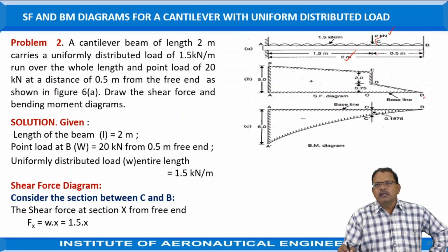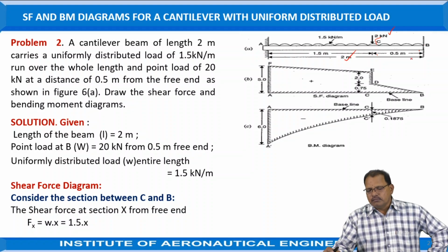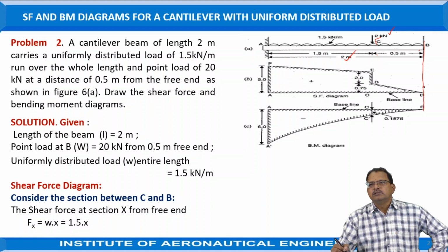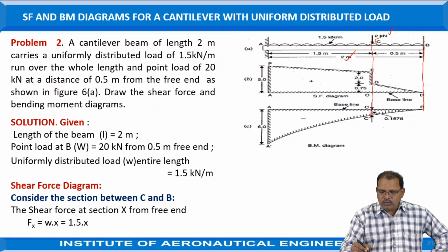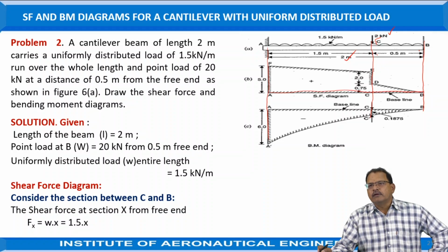Now from the diagram, in order to draw the shear force and bending moment diagrams, after drawing the beam and representing the various forces acting on it, draw vertical lines passing through the points at which the loads are acting, that is at the B position, at the C position, and one more at the A position. At a convenient distance, draw a horizontal line to represent the length of the beam in order to draw the shear force diagram.